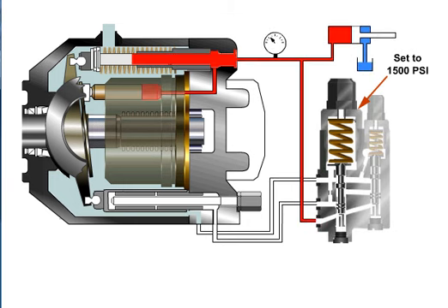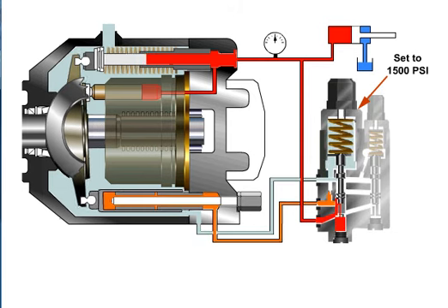When the cylinder reaches the end of its stroke, pressure rises at the outlet of the pump as the fluid's flow path is blocked. This pressure forces the compensating spool up, allowing the pressurized fluid to energize the de-stroking piston and push against the swash plate, forcing it to a vertical position. With the swash plate vertical, the pump is now de-stroked and the pressure at the outlet port is maintained at a constant level. A very slight amount of flow is produced to maintain de-stroke pressure. This flow is bypassed into the case and carried back to the reservoir through the pump case drain outlet.